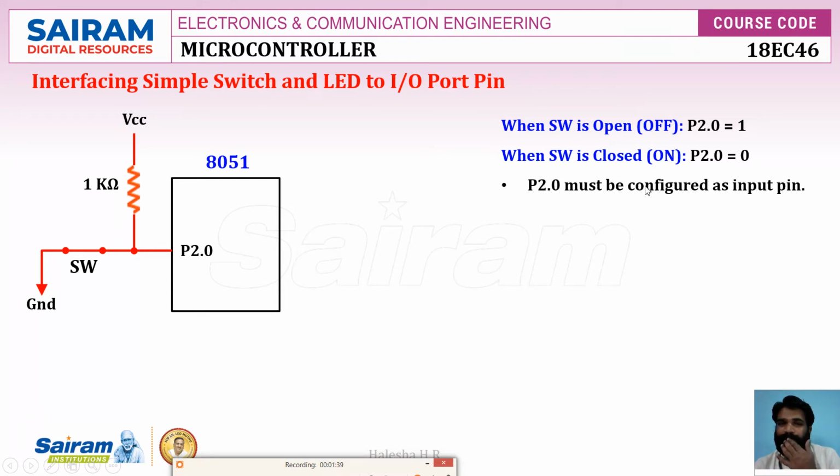Clear? This must be configured as an input pin because we are reading the status of the switch. The microcontroller reads the value, so it should be configured as an input pin. That means we need to write one to the corresponding latch, as I explained in the operation of ports.